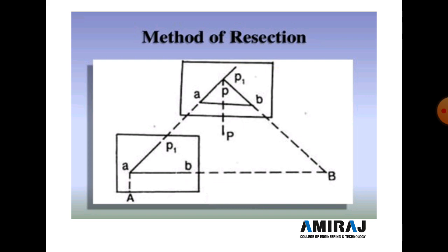With the help of the alidade, touch the point a, bisect the ranging rod at P, and draw the line as an imaginary line. Now a point P1 is marked on this line by estimating with the eye. Clear? So it is marked as point P1.